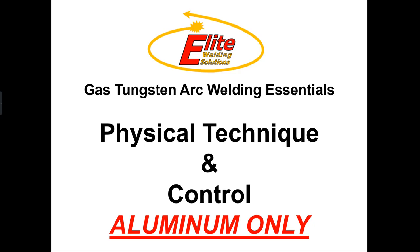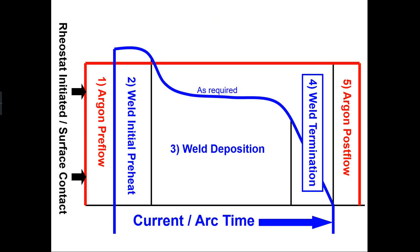So physical technique and control. I want to define a little bit, and I like to draw pictures or like to draw something to put in your mind to understand what this process is doing and how we are controlling it. What are we in control of and what aren't we? So the whole thing begins with a pre-flow of argon. Now usually we've got a torch set up in such a way that the pre-flow runs for a few seconds before you start to weld.